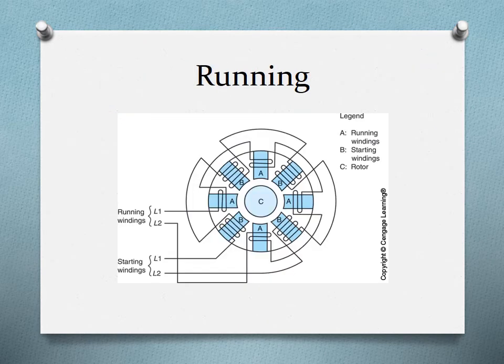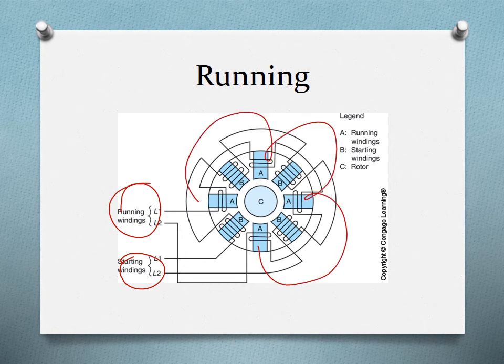Okay, this is the motor with the running winding. If you can see, there's different kinds of winding. There's a start winding and there's a running winding. So the start winding will engage, then as we reach the desired RPM, the centrifugal switch will cut off the winding, and the motor will keep spinning, but it will not increase the speed. So the startup winding here, going to these loops, will keep adding speed until we reach the RPM we need, then it will cut off the startup winding. And you can usually hear it click in a lot of those motors.